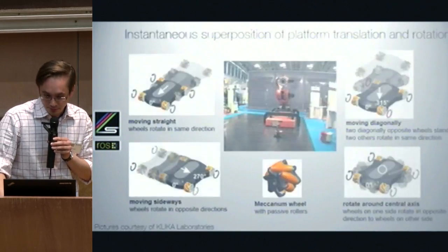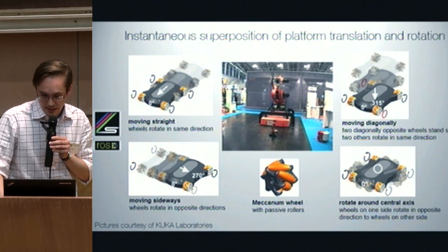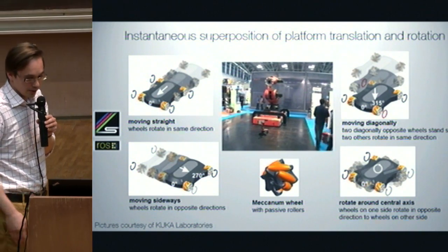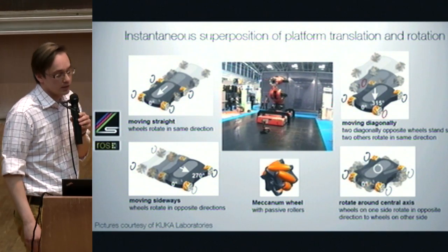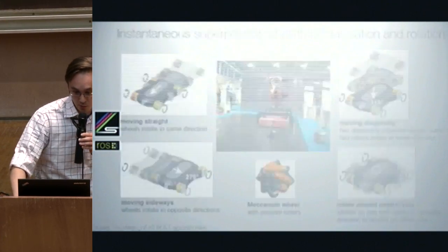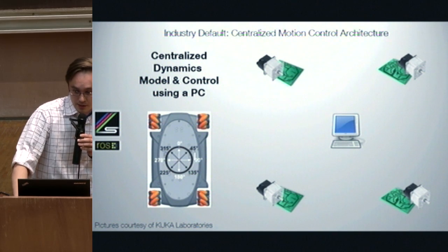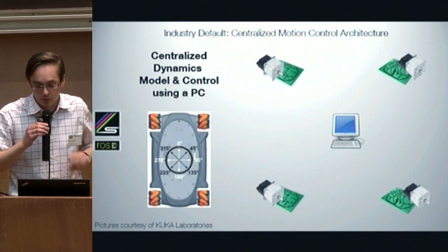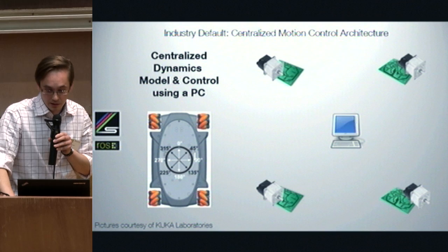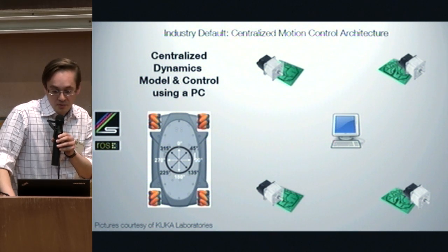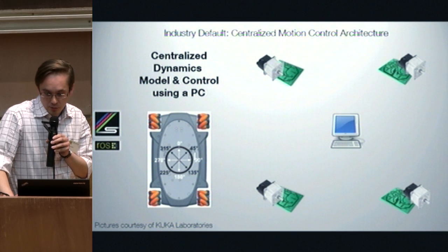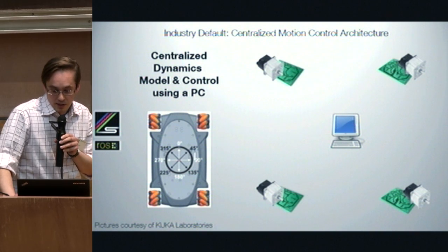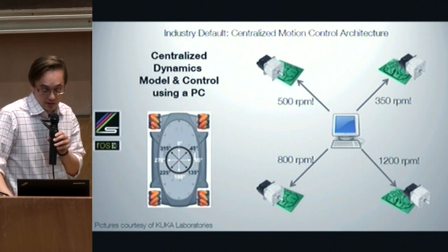And to give an example, I guess you know about omnidirectional bases using mecanum wheels, like the KUKA U-Bot has, for example. And classically, position control is carried out by the PC using a model dealing with the mecanum wheels and odometry, by setting speed and reading positions of the 4 wheels, which needs to happen a lot of times per second to be precise.